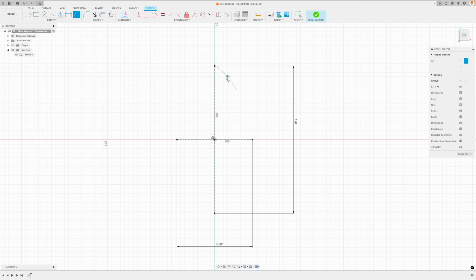If I go in between those 2 points, you can see that it creates a small section of an arc. If I go outside of that, look what happens. Now we get this giant arc. So this might frustrate ones too, but the principle involved is just start simple. Start with one sketch element at a time, constrain it, lock it in before you move on. Anyways, there we go. I'm going to create that.